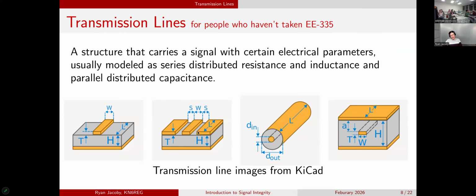When you do coplanar waveguide and you have your ground plane next to and also potentially below your trace, now you have more capacitance to ground, and you're going to need to make your trace thinner to compensate to hit the same characteristic impedance. You're not adding inductors to your trace. You're adding vias between the ground plane on the side of your trace and the ground plane below your trace, and in parallel the equivalent inductance is less.